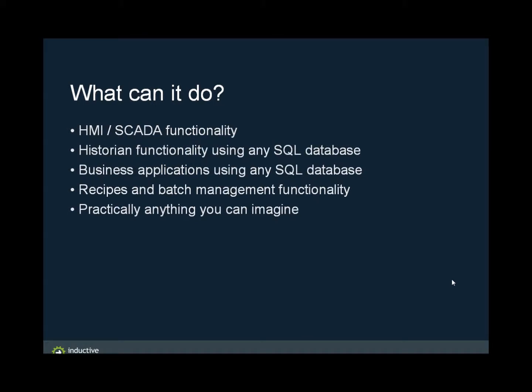Ignition is modular in nature, and the modules can be used to accomplish a variety of different things. You can use it for HMI SCADA functionality. Some people will use just the SQL bridge as a historian. You can log to any SQL database of your choice. So we have all the drivers, whether it's MySQL, SQL Server, Oracle, Postgres, IBM DB2, whatever you want to use. You can also use it for recipe and batch management and practically anything you can imagine. The last line's a little cheesy there, but it's really because of the binding architecture behind the components of Ignition that make it so flexible.